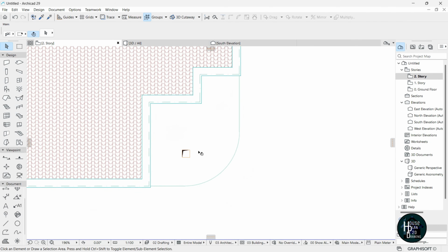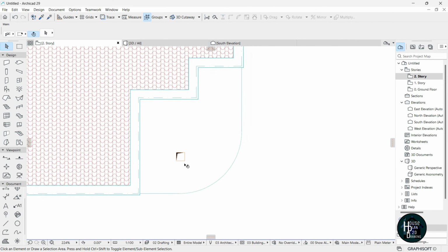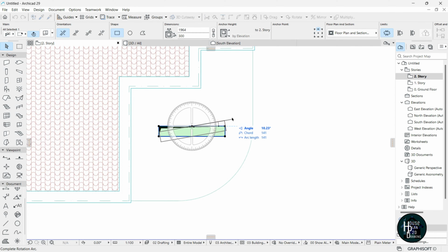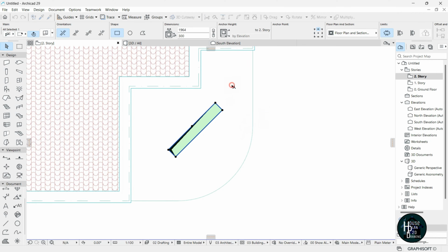Okay, so we want to try and edit this opening to something of our taste. Now once you just select this, select this edge here, select the offset edge and just move something forward like this. Okay, press Ctrl D, move it to the center, press Ctrl E and try to just rotate it like so. Press Ctrl D and just move it somewhere around here like this.